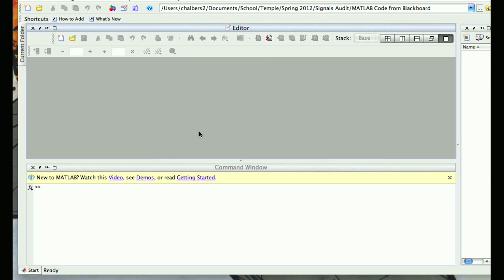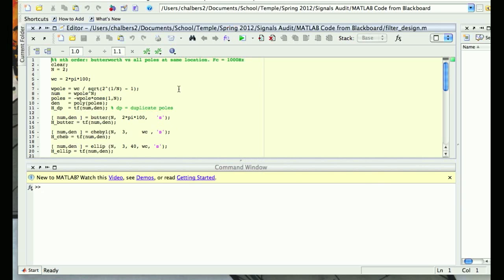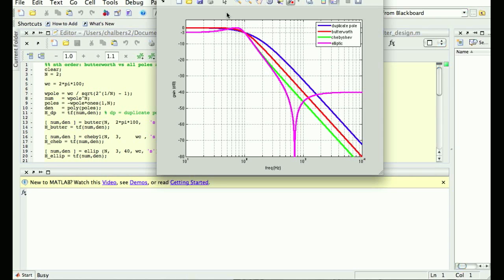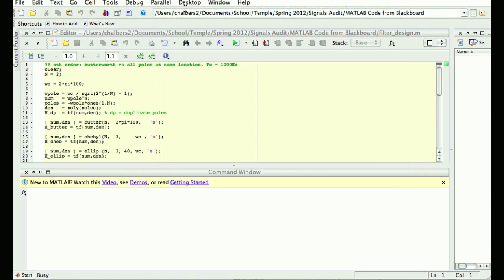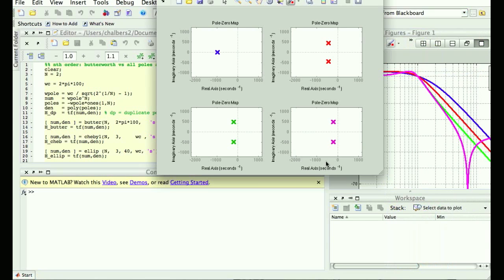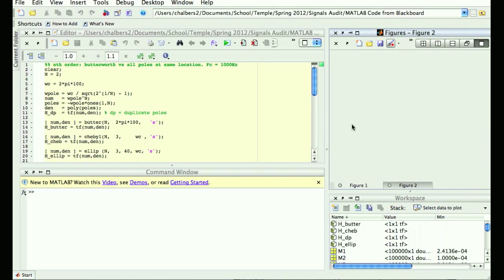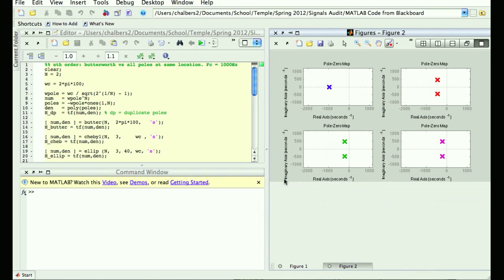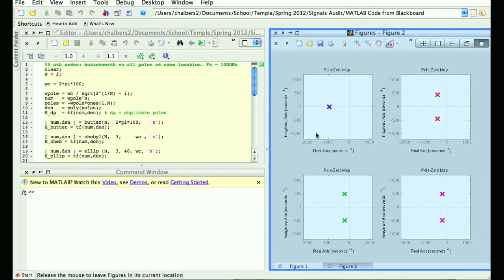What we talked about on Monday was how to design a filter, and the different kinds of filters. We said there's first order and second order, and second order has two flavors, underdamped and overdamped. We talked about how you can filter things and calculate what the output cosine is for an input cosine. Then we talked about the need for steeper filters. Sometimes two poles might not be enough. Why not do three poles, or four? Why not have a filter that rolls off more aggressively?